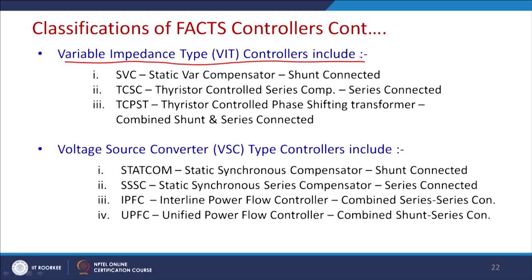TCSC, which we saw a few slides before, that is thyristor controlled series compensation, is an active capacitor and it is a series connected device. Similarly, the thyristor controlled phase shifting transformer is used as a PAR, power angle regulator. And the other type of FACTS devices